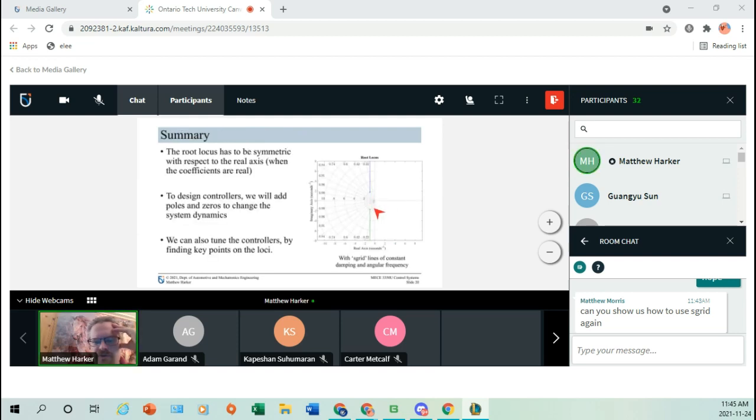That would be that circle there, which means those poles are on that circle at that damping ratio point, which in this case is 1. And the locus goes out from those points. So we have constant natural frequency as the radii, and the rays from the origin, the angles, are essentially the damping ratio.